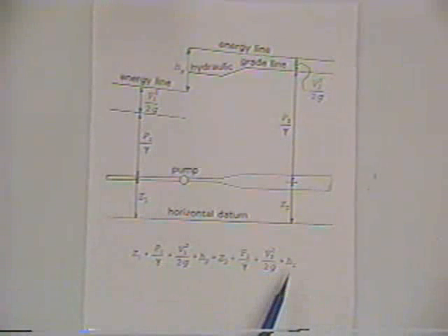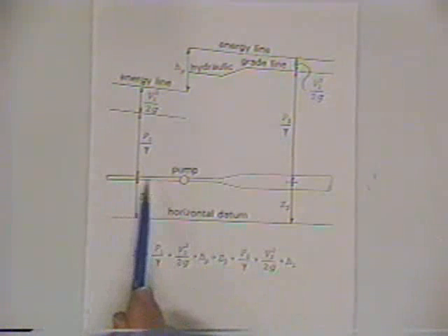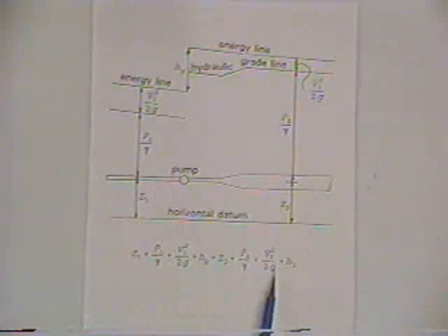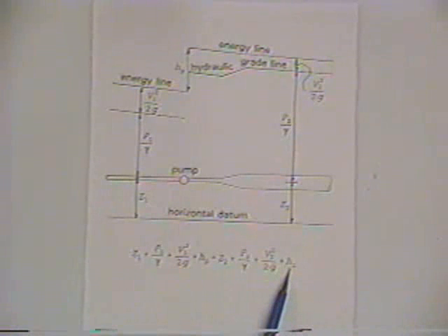And then a key term in many applications is the head loss term. We were able, in the pitot tube example earlier, to assume there was no head loss. We were picking points adjacent just to the entrance of the pitot tube, but in some pressure conduit of some length, there's going to be head losses. And so we've got to be able to estimate head losses. And that's the direction we're going now, is to look at ways of estimating the head loss term in the energy equation.